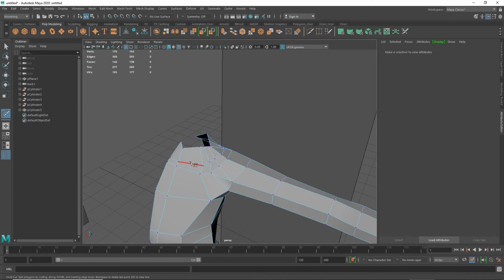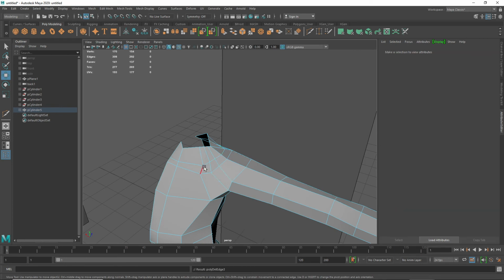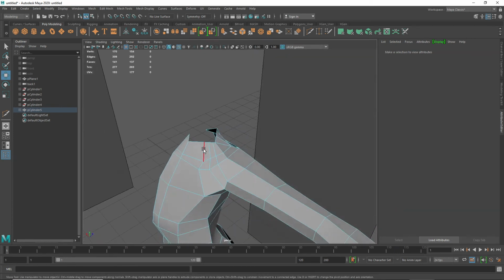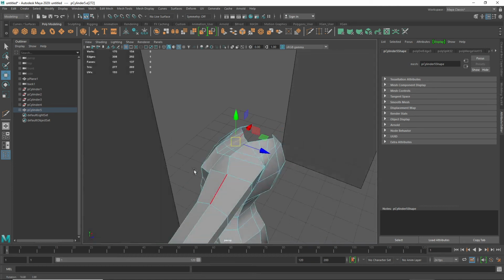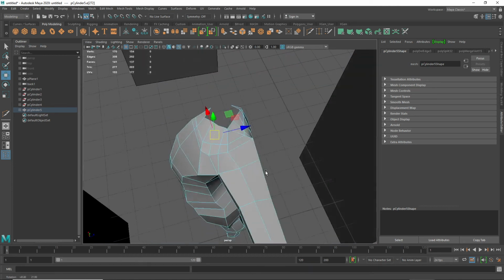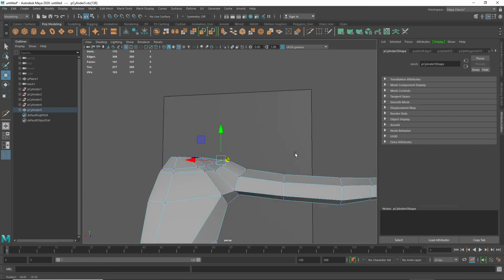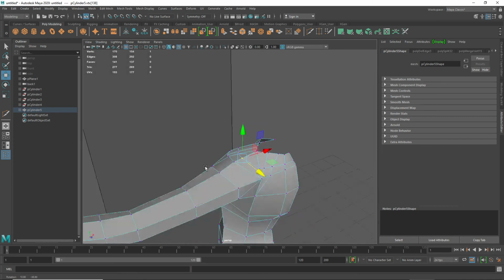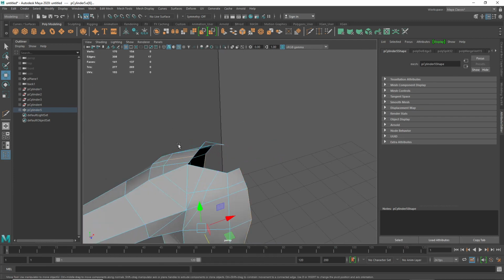Now, a lot of this is ultimately control backspace to delete. A lot of it seems like it's starting to bunch up here, and that's something that we don't want happening. So I'm just going to start blending some of this a little bit apart here. And you can see that that makes that front look good. We're going to grab the vertices here and just center them so we get more of that radial kind of feeling. And then we've got our shoulder muscles. So that's looking good.